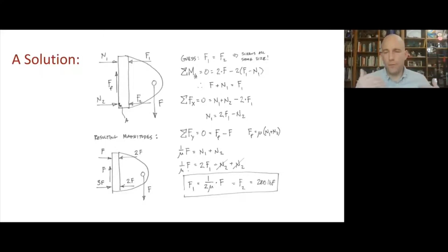The screws have complex geometry with these threads, lots of stress concentrations, and they tend to be weak points if you put a screw in bending. So we want to avoid that.